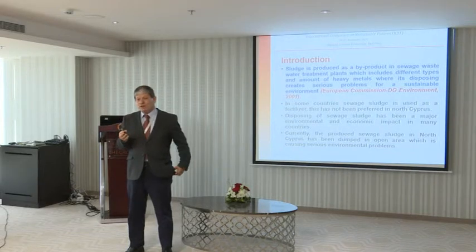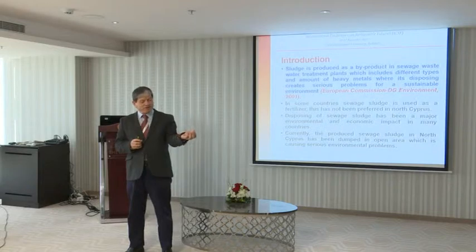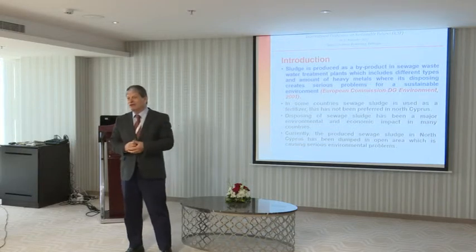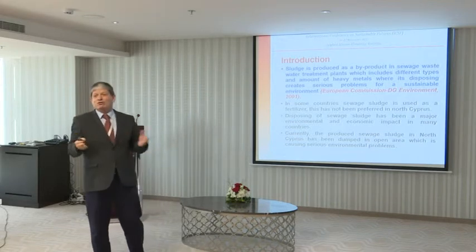Because in foam concrete we have a problem. We studied foam before. The foam itself has about 40-50 kilograms per cubic meter, but the aggregate or the cement used is a lot heavier than this. So there is segregation, separation, and weakness. How can we improve foam concrete?